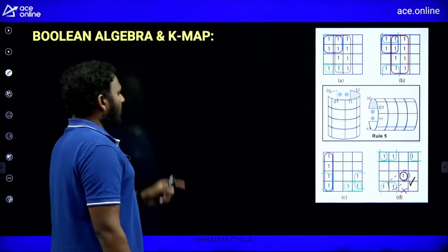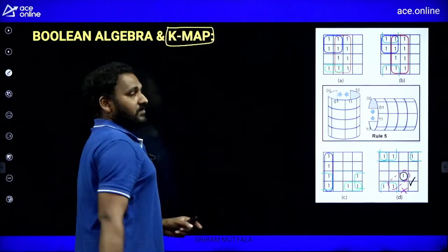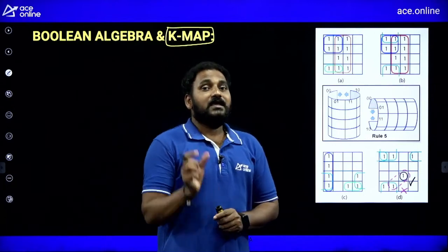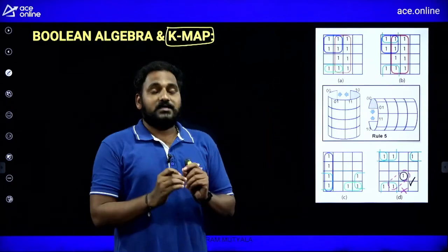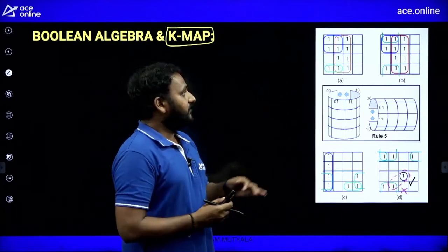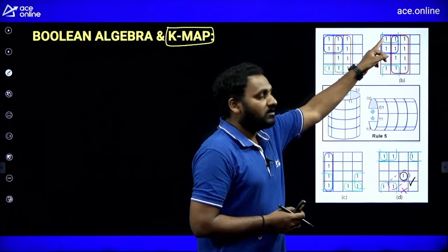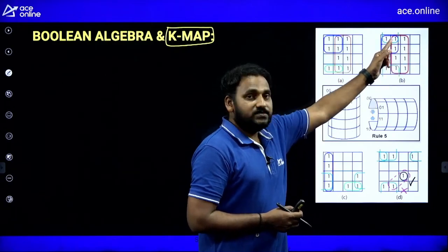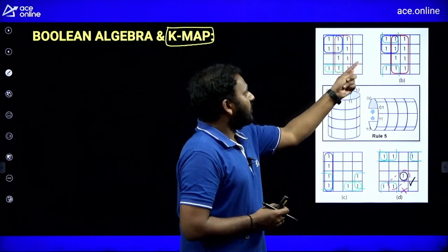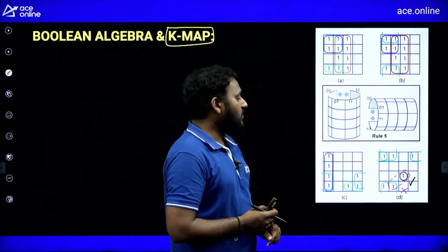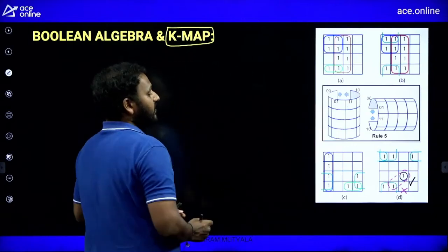And along with Boolean algebra, just try to have a look over the K-map, Karnaugh map minimization. No way to frame questions on this, but just for the safe side. If you find 4 adjacent cells, a quad, we can group it and take the common terms. Octet, 8 minterms, adjacent terms, you can group them. Folding is possible in K-map, but remember offset and diagonal grouping is invalid.